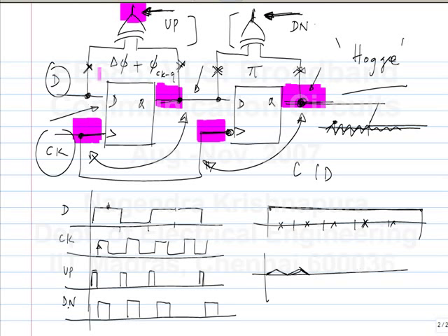Subtract the waveforms. Then, no, that's what happens, right? I mean, when you have two current sources in opposite direction, when it goes to the loop filter, it's already subtracted. That's not what he was saying. What he was saying was, instead of having this separated in time, you have it time aligned, so that more or less for the entire period they cancel out. Okay.